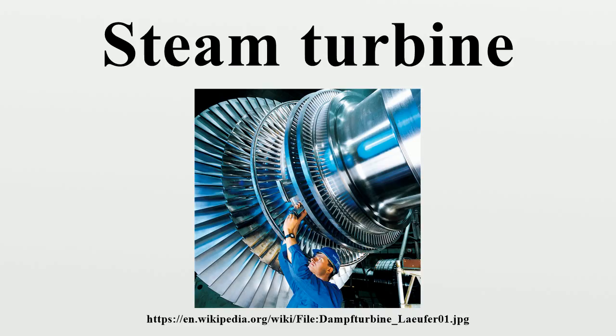Blade and stage design. Turbine blades are of two basic types, blades and nozzles. Blades move entirely due to the impact of steam on them and the profiles do not converge. This results in a steam velocity drop and essentially no pressure drop as steam moves through the blades. A turbine composed of blades alternating with fixed nozzles is called an impulse turbine, Curtis turbine, Rateau turbine, or Brown-Curtis turbine.